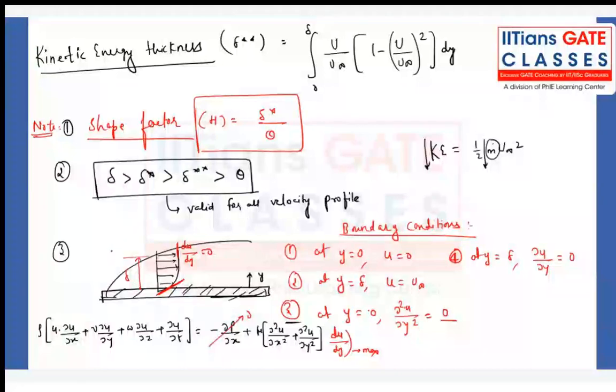So now when you just do that, for the flow over the flat plate, dou p by dou x will be 0, because here, everywhere the pressure is P infinity. Now there is no penetration, so v will be 0 at y equal to 0. I'm applying this at y equal to 0. Omega will be 0, steady flow.